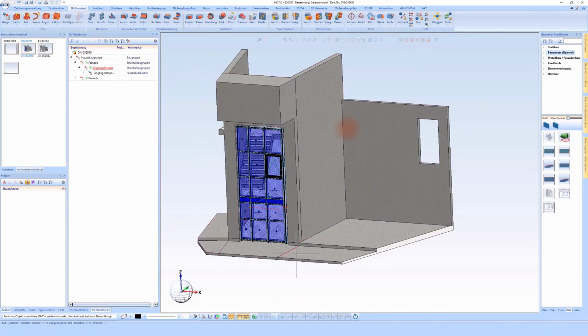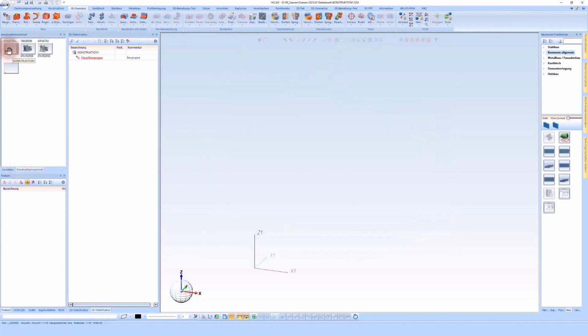And to keep everything up to date in various areas, I naturally don't want to work with too many sheets, because that makes the drawing cumbersome. Therefore, I have referenced this to bring in the individual elements into my drawings, meaning I can incorporate each external reference into the drawings and edit them more specifically.